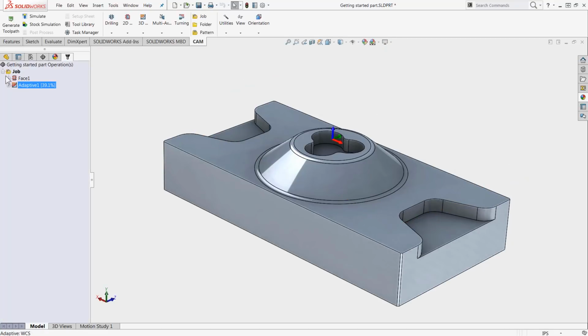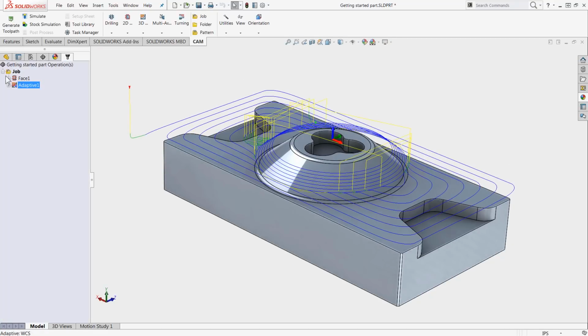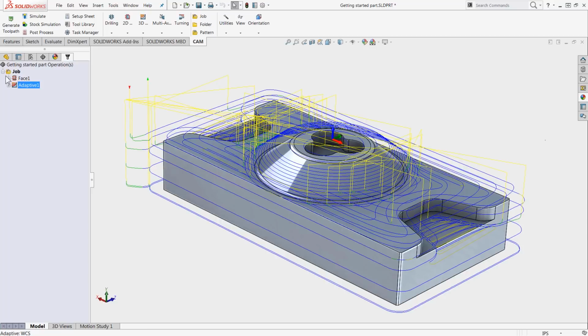This is a lot easier than if you have to go in and change a bunch of settings and then come back and try to figure out what changed what. One thing that stands out is that the tool will machine all the way down to the bottom of the part. I was kind of planning on holding on to this in a vise.